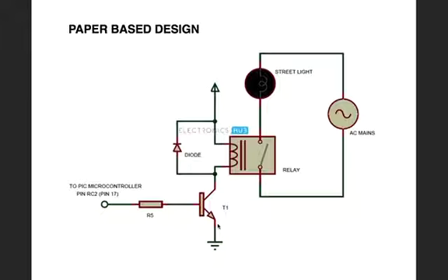If we talk about the working, we use both an LDR and an RTC in the circuit. We use the LDR because otherwise there is no chance of saving energy on the street lights. The lights glow as soon as the intensity of light on the LDR decreases, and when the intensity increases, the street lights are turned off. So the LDR is used to determine the intensity of light on the streets, and according to that, we can vary the intensity needed.